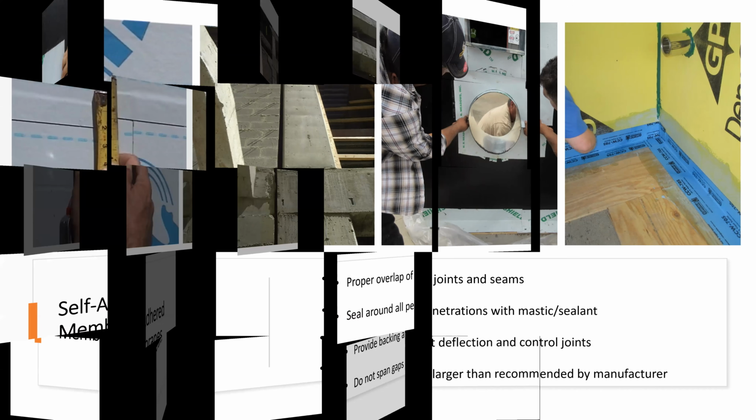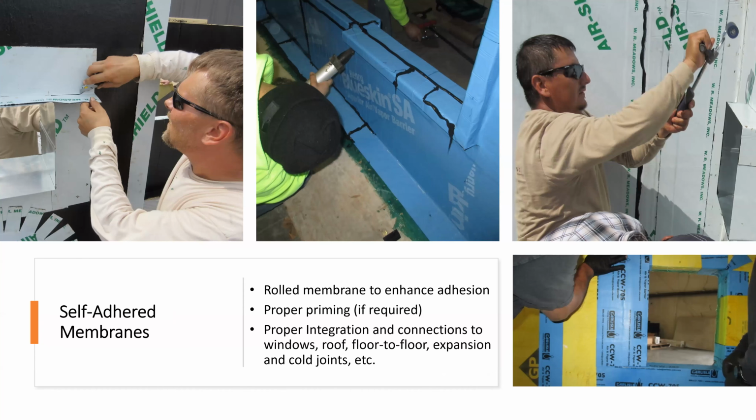The next thing that is very important is rolling and priming. It makes a massive difference in regards to using a hand roller to really push this into the substrate. There is quite a bit of a difference between just kind of patting with your hand, making sure it's stuck well, and actually rolling it. So all manufacturers say it has to be rolled with kind of like a countertop roller where you put your full weight into it. Okay, so that actually becomes a very, very important purpose.